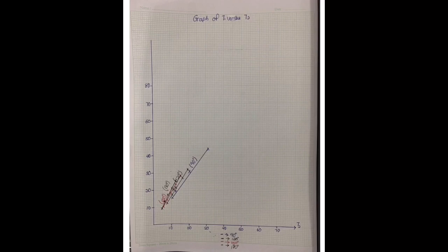Today I am here to discuss the discussion of the topic 5 laboratory, which is belt friction. Here I have plotted a graph of T1 versus T2 according to the angle of lap on the same graph paper, whereby the data is based on T1 and T2 from test 1. Based on the results of test 1, we can anticipate that as the angle of lap increases, so will the driving force. When the angle of lap increases, the value of M1 needed to stabilize M2 decreases.